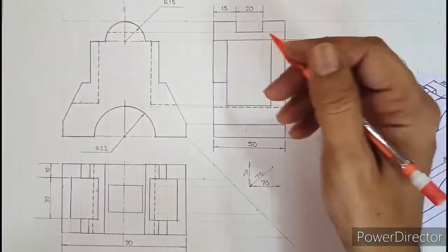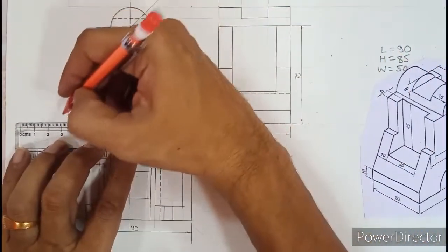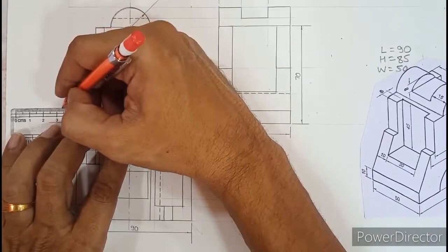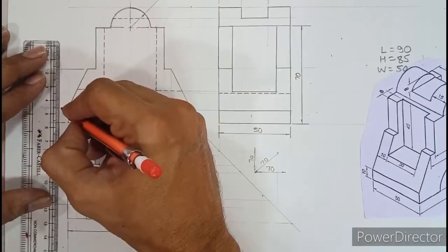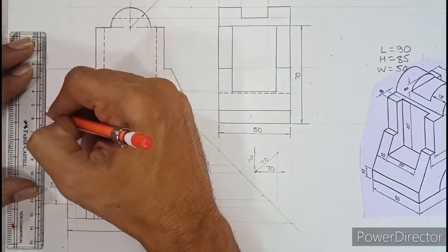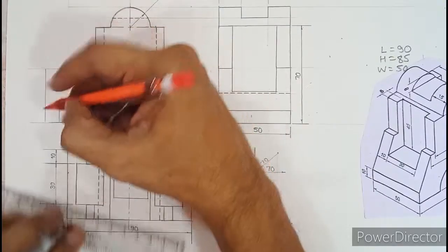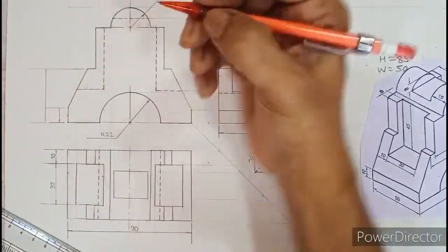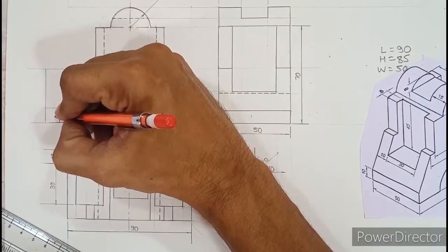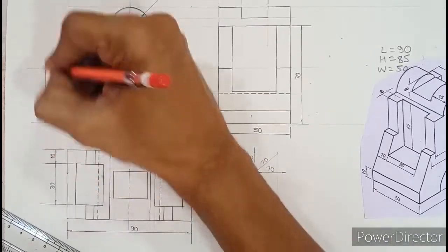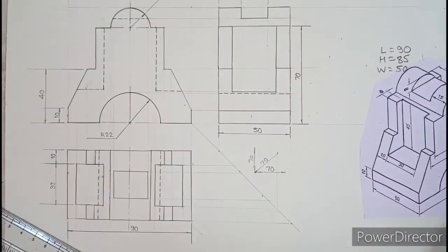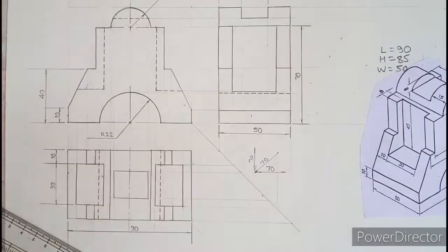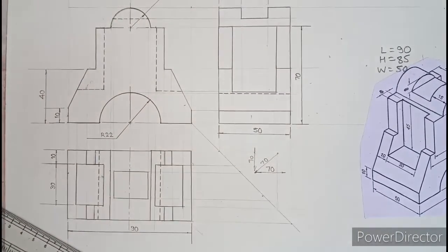so as to complete. So in the front view what one can do is, we can show this 10 which is shown in the front view. Along with that, this 40 can also be shown. So this dimension is 10, which is given in the question, and the behind dimension is 40. So this 10 can be shown here. Always write above the line, 10 and 40 shown here. Okay, so these are the complete 3 views required for orthographic projections.